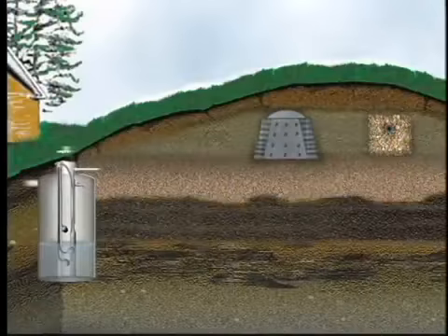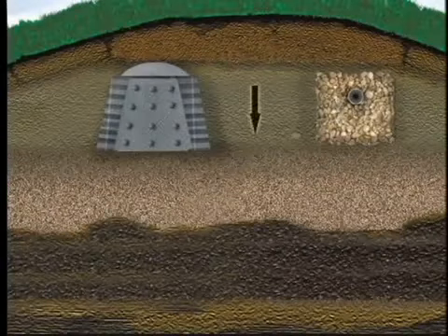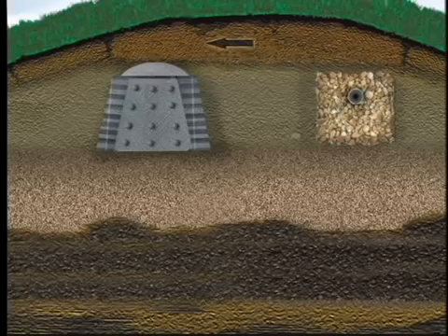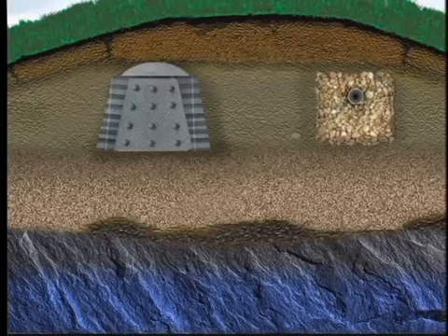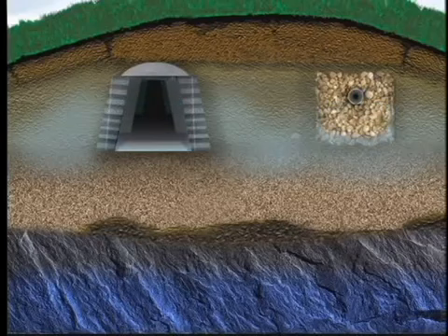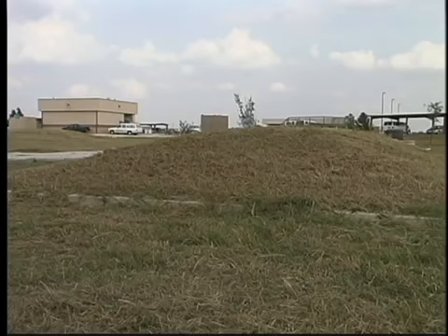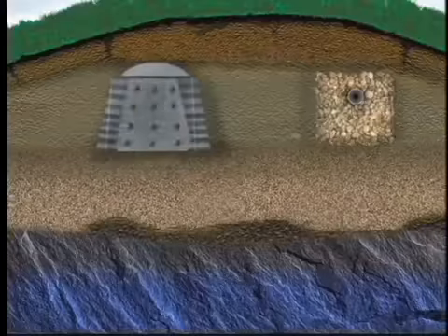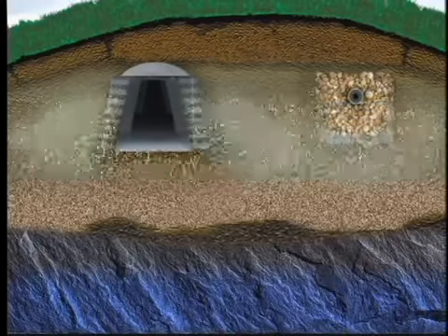A mound system consists of a pump tank and mound land application system. The mound has several layers including permeable fill material, a wastewater distribution system, a sandy loam cap, and topsoil. The mound system is ideal for areas with minimal soil between the surface and either groundwater or bedrock. A drain field is created above the natural soil surface to allow final treatment of wastewater. In essence, this is a traditional low-pressure dosing system built above ground level. Its layers work in combination with native soil to treat the wastewater. Like its traditional counterparts, it relies on the soil microbes to provide the natural treatment process.